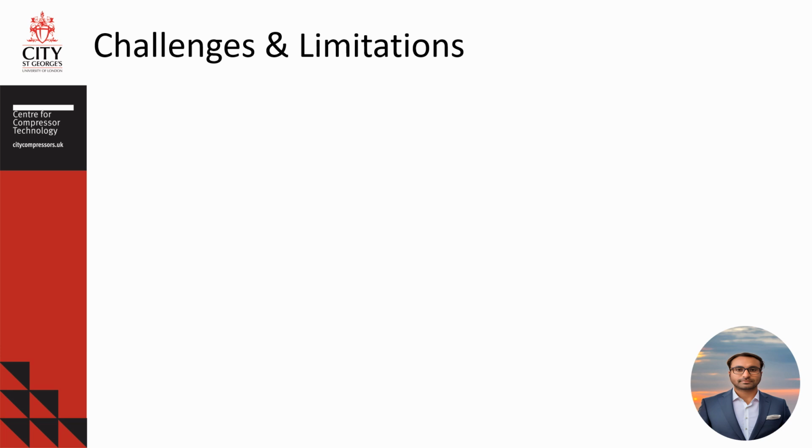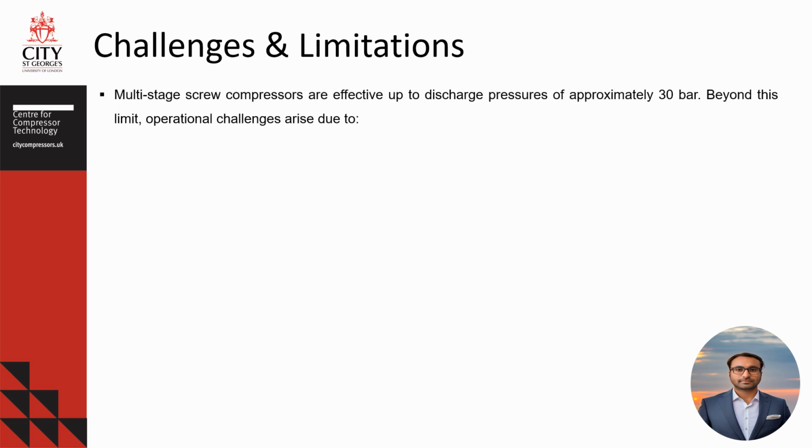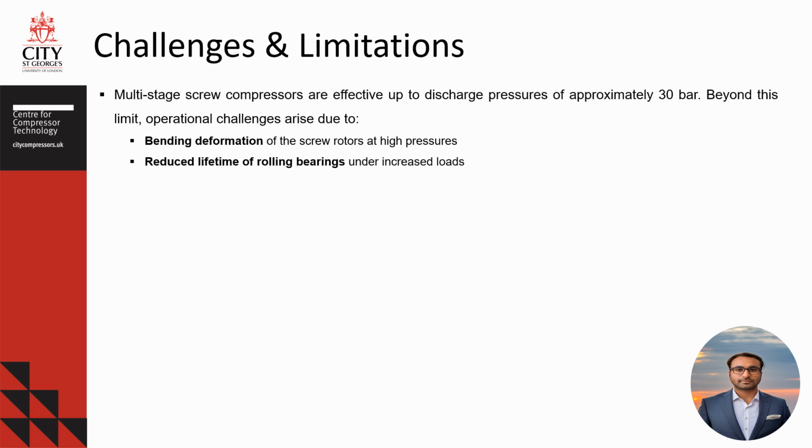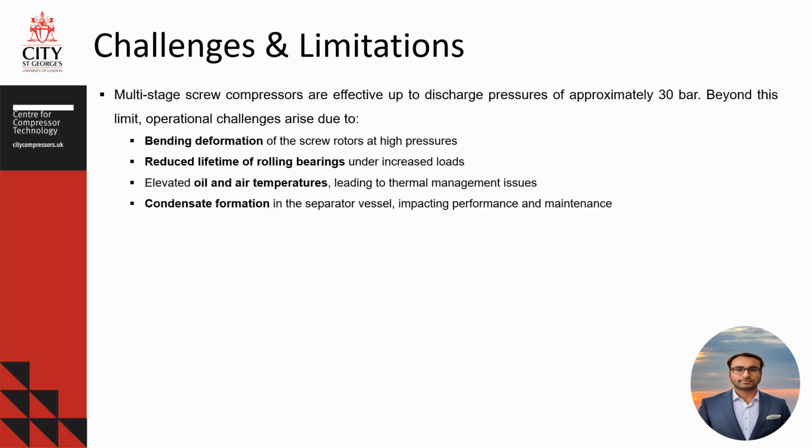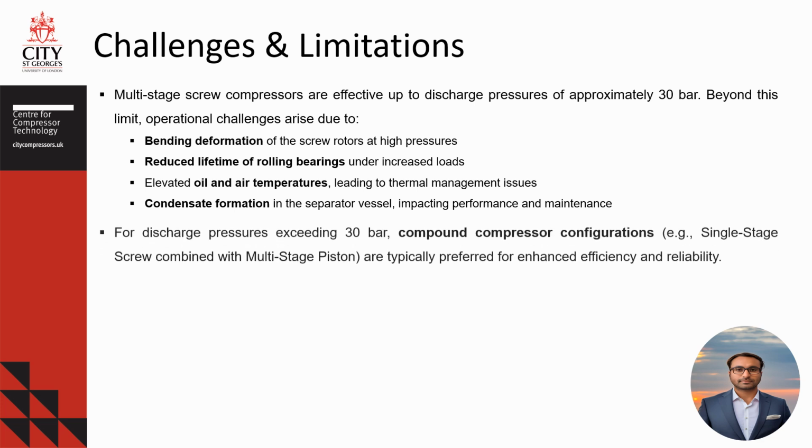Multi-staging has its own challenges and limitations. Multi-stage screw compressors are effective up to a discharge pressure of 30 bar. Beyond this, operational challenges arise due to the bending deformation of screw rotors at high pressures, which leads to rotor deflections. Other issues include reduced lifetime of roller bearings under increased loads, elevated oil and air temperature, and finally the condensate formation in the separator vessels, which impacts the performance and maintenance.